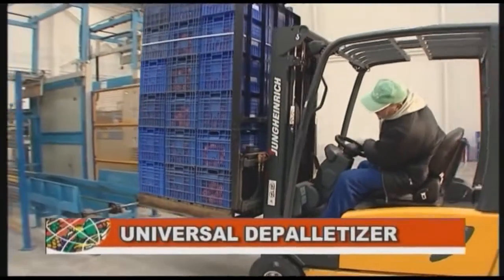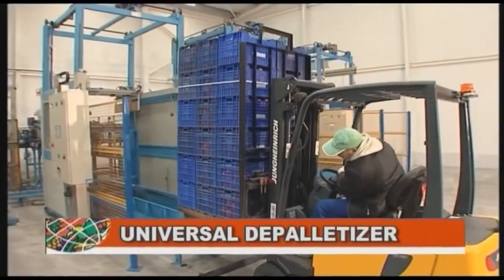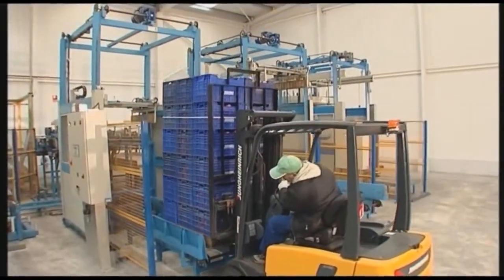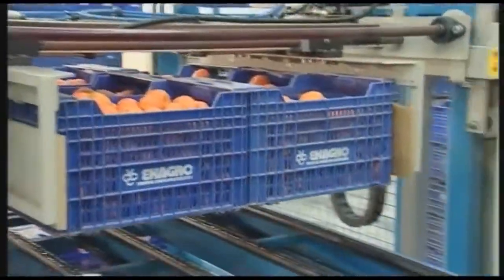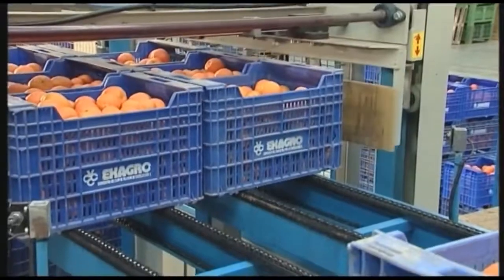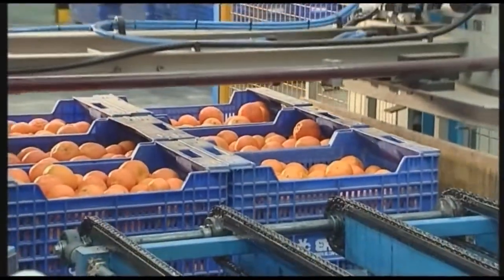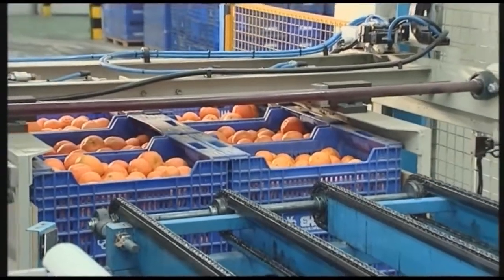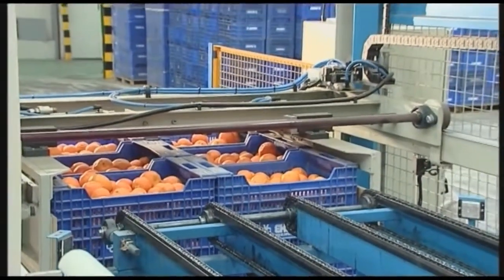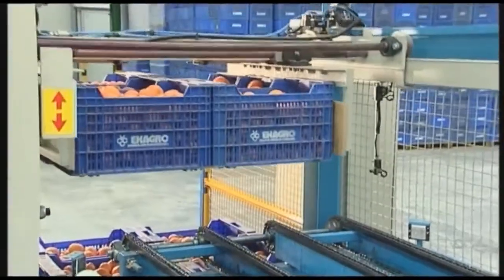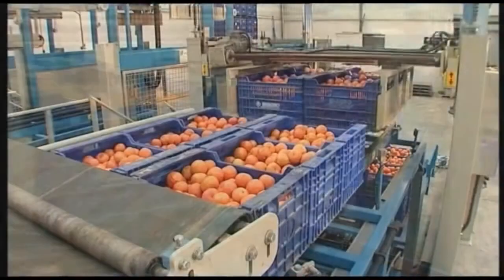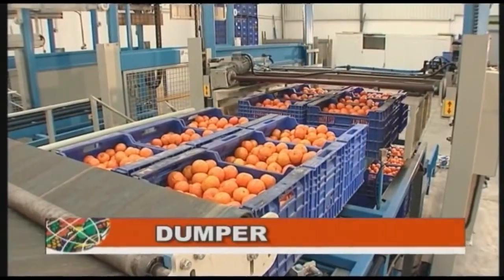The full-layer depalletizer is designed to destack layers of boxes from the pallet and place them on the chain table, dosifying the boxes 2 by 2. The depalletizer clamp is equipped with 4 rubber-padded arms to adjust to the small differences in size between different box types. Following this, the fruit is unloaded with the automatic rotating dumper. The operations are carried out in a secure, careful manner, providing a continuous flow of fruit.